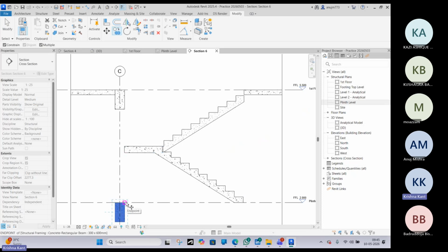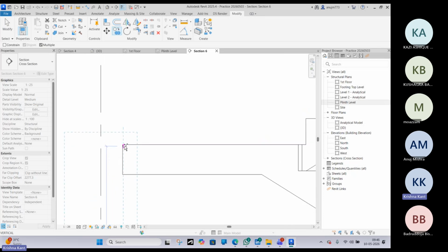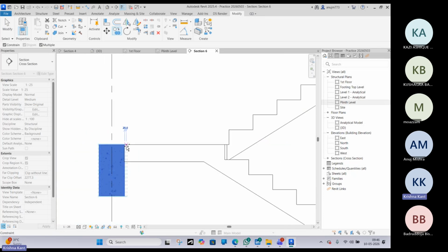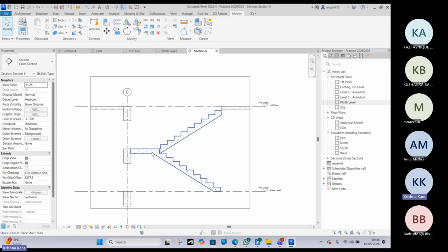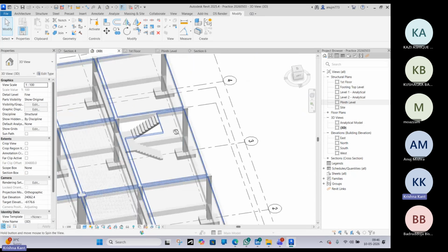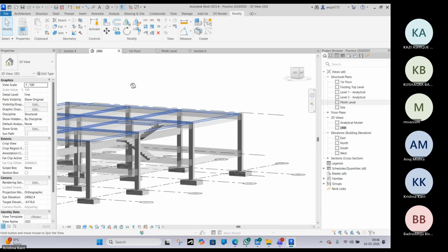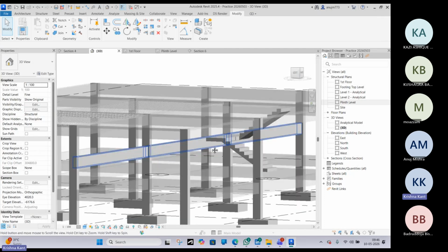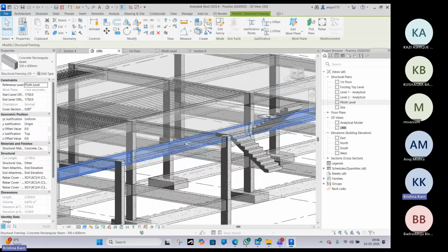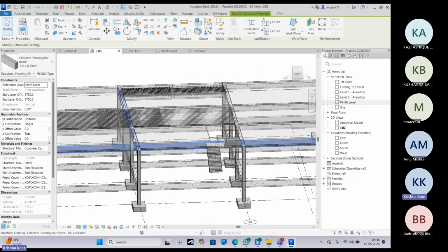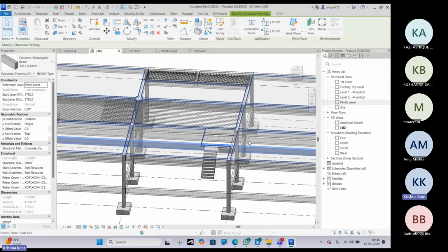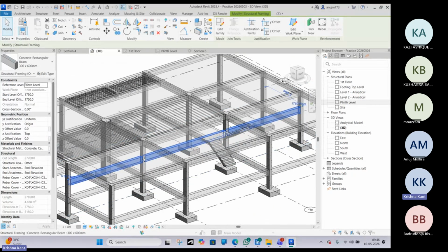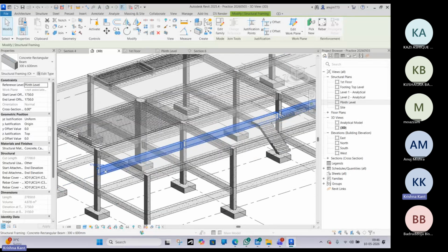Okay, so copy this beam, remove the constant and paste it along this stairs mid landing. Okay, so as you can see, we will be having one more beam. Now the beam will not be this big. It should be connected to this column only, to support. No need to provide till this area.